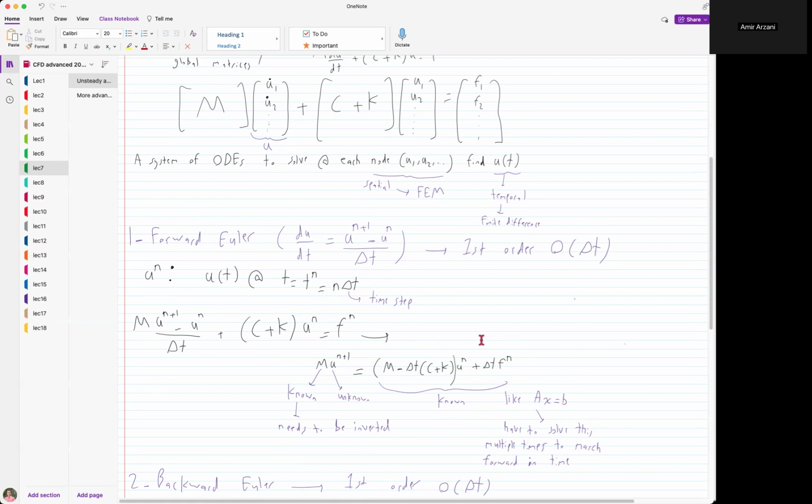Okay, now, I forgot to mention another important thing. Another reason that you might need to consider the advection diffusion equation unsteady, even though all these terms are steady, like steady velocity, steady boundary condition, is that it could help with your convergence. So if you treat it that way, it could make it easier for your finite element solver to converge rather than directly ignoring this unsteady term and directly solving it as we did for a steady problem.